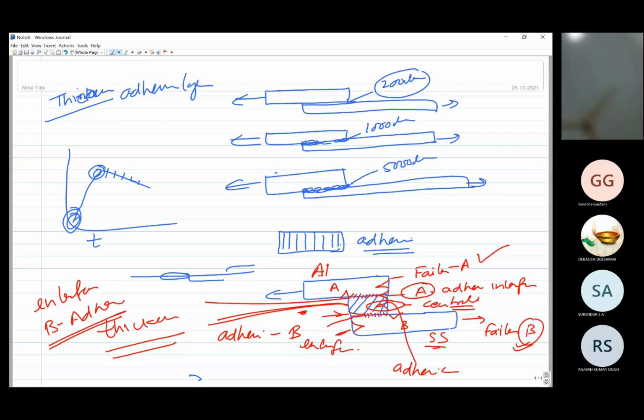Okay, so base metal nugget pull, those are the spot weld related failures, but these failures are a little different from what we normally see in the case of spot welding. Okay, so in this increasing phase, the strength basically corresponds to the base metal and adhesive interface failures. And when thickness starts increasing, then we will say this is the adhesive failure.